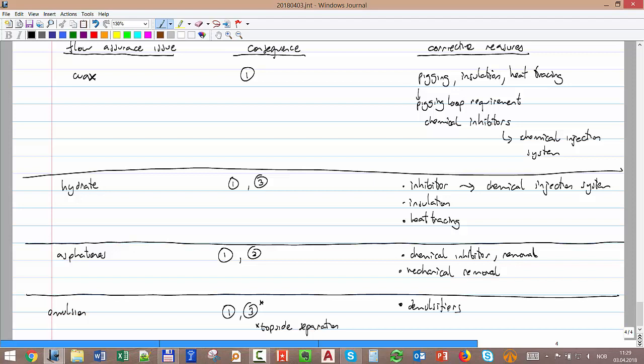Just be aware, sometimes they work. Sometimes they have some effect in the interfacial phenomena, and sometimes they can make the emulsion less stable. But sometimes they have limited effect. It depends on the shear, depends on the characteristics of the fluid, but in truth it's a chemical that we inject to maybe reduce the peak, maybe make the peak disappear, to try to make the emulsion less stable, to promote separation. What else do we have?